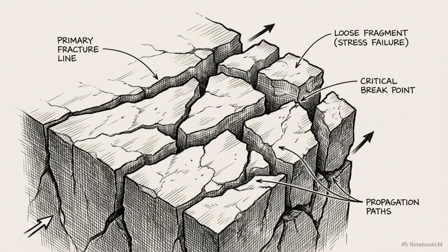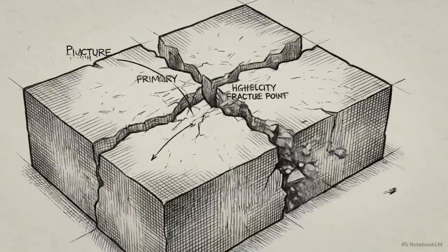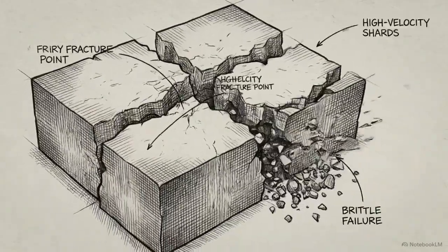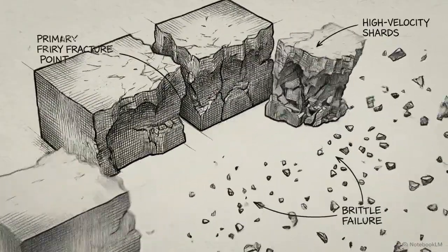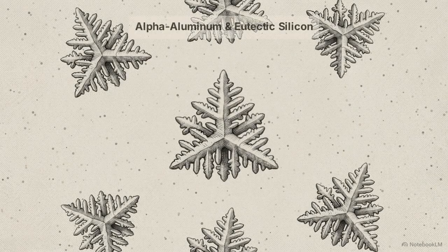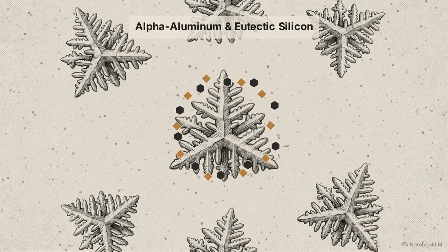If the alloy is oversaturated with silicon, the entire component becomes fragile. Silicon is the indispensable armor of the alloy matrix, but if improperly balanced, it becomes the exact mechanism for fatal brittle fracture. To push mechanical limits further, tertiary elements like copper and magnesium drive precipitation hardening. This is a mechanism where tiny, hard particles form within the metal matrix to impede atomic movement.